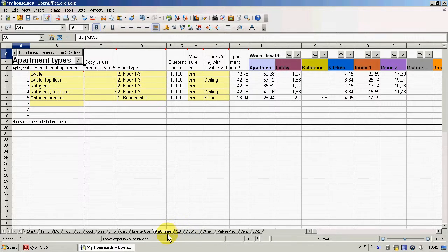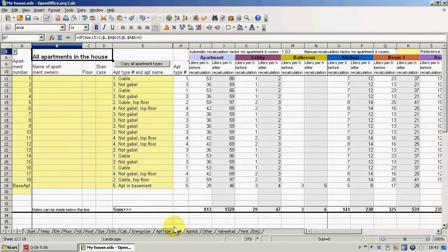It's very important that you use all these three sheets to get the radiator presetting values and not directly just take the water flow in liters per hour from this sheet, for example. More information about these sheets you can of course get if you look at the tutorials by pressing the question mark button on each of these sheets.